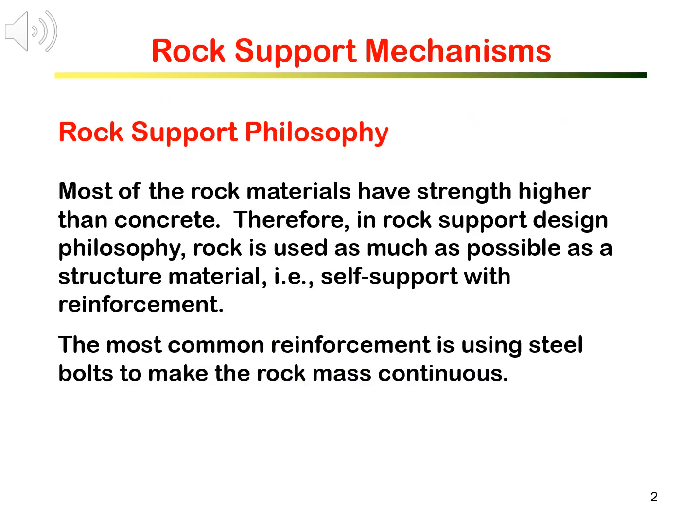As we have learned in rock mechanics, most rocks, except a few weak sedimentary rocks such as mudstones and shale, are stronger than concrete. For example, granite is typically 5 times the concrete strength or more. Therefore, in rock support design philosophy, rock is used as much as possible as a structural material, i.e., use the surrounding rock to be self-supporting.